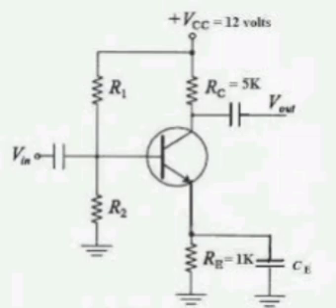Thus the meter scale can be calculated by computing the fraction of full scale S for a given resistance Rx in terms of Rx and the meter resistance Rm. In order to determine the relative scale values for a given value of R1, the half scale reading may be found by dividing 1 by 2 and solving for RH. RH equal to R1 Rm by R1 plus Rm.